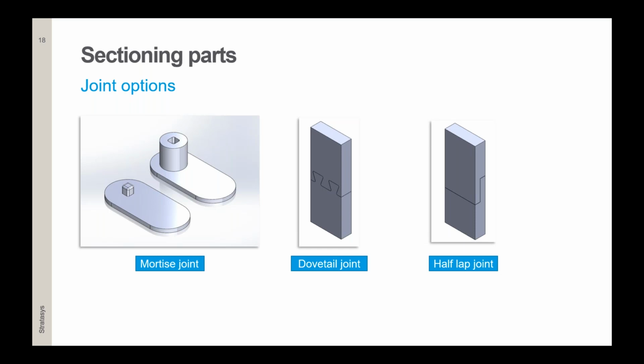You can also use a combination of those joints to increase bond strength even further. If you have to use fillets, then a radius of 1 millimeter should be added, if you are using something like in this image here. And you can also use pins to help position the parts for bonding and align them better.